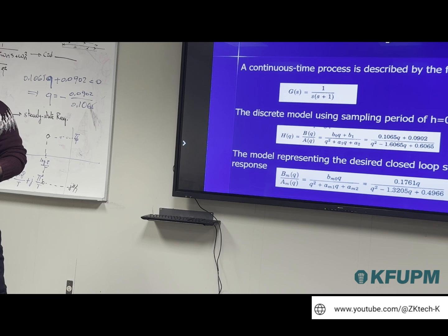Is there a difference between the oscillation due to zeros and the oscillation due to modes? Yes, there is a difference between the oscillation from poles and the oscillation from zeros. The dynamic impact will be different. It's like having s squared plus 2 zeta omega n s plus omega n squared in the numerator. Is it the same as having it in the denominator? It has an effect.